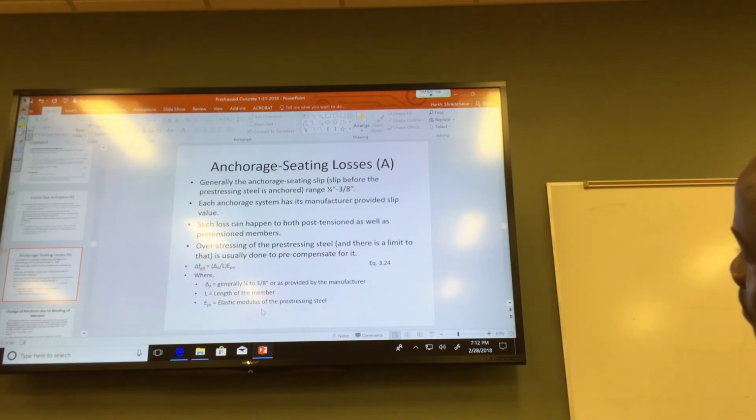So I should be using 490 really, right? My strain is dependent on stress. Applied stress is 500 or 490. I thought I will put 500, but I ended up with 490 because I lost because of the shrinkage or shortening of your elastic shortening of your concrete member. So the applied force is 490, right? So the elastic shortening should be based on 490, right? But if I put 490 as my applied force, it's going to shorten in a different manner. So 490 is not accurate, right?